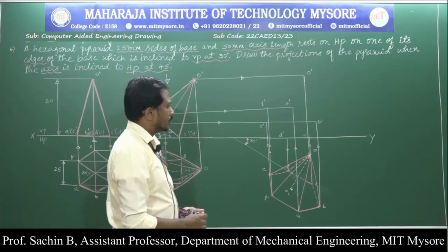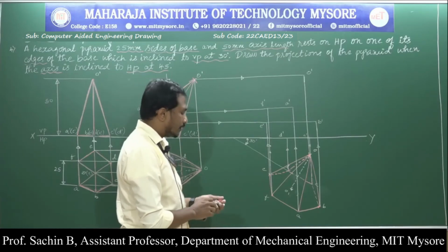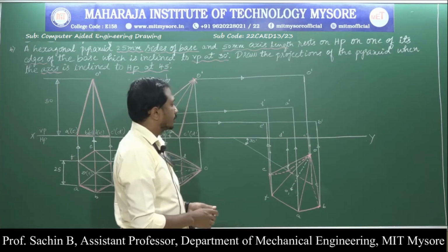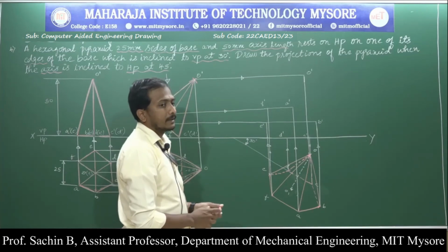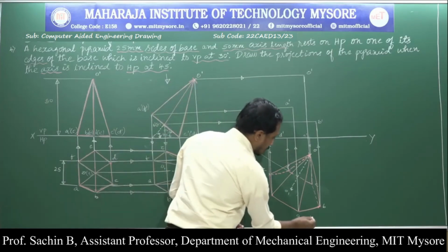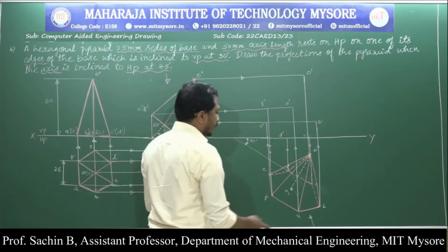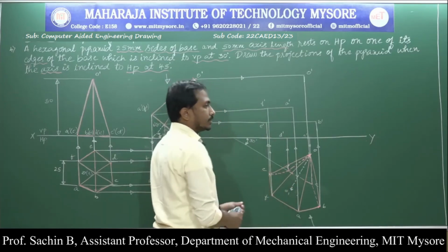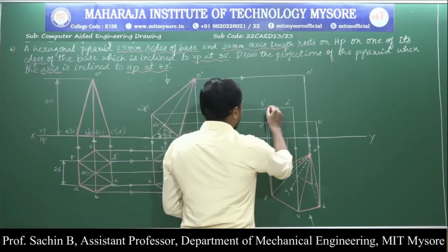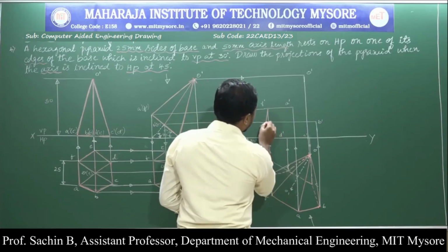According to it, first for the easy purpose, I am going to go for the second condition first, that is nothing but the faces and edges near to the observer are clearly visible. Based on that, I am viewing the object from the front view. From the front view, the base edge is clearly visible for me. I am going to complete it now. The base edge.